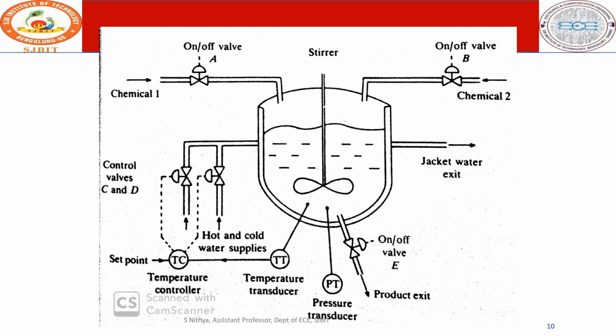So the reaction temperature should be monitored, and when the timer indicates that the reaction is complete, switch off the controller and open the valve C. Okay, open the valve C. So why are we opening the valve C? Because it carries cool water to cool down the materials. Okay, and switch off the stirrer. Okay, and after that